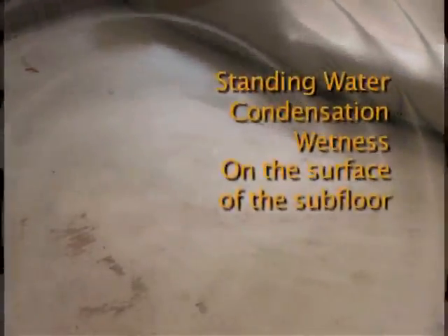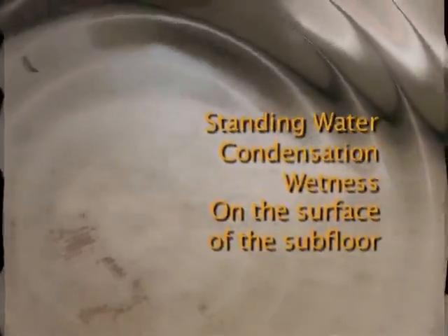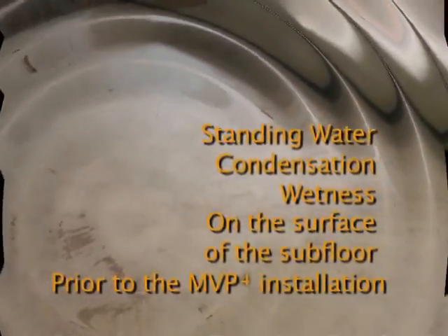To ensure a quality MVP4 installation, you will need a dry, clean, dust-free flat substrate with no sealers or bond breakers present. To accomplish this, you must first inspect for standing water, condensation, or wetness on the surface of the subfloor prior to the installation of MVP4.